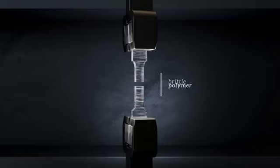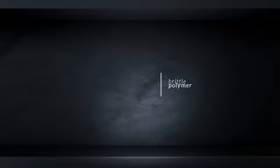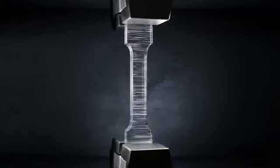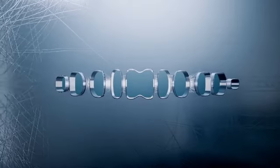A unique phenomenon associated with the failure of brittle polymers is crazing, where a network of fine, linear features form within the polymer just before fracture. These features are tiny voids within the polymer, but unlike cracks, the voids are bridged by fibrils of polymer material.